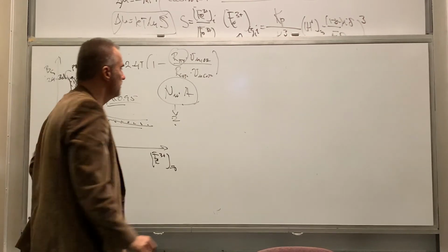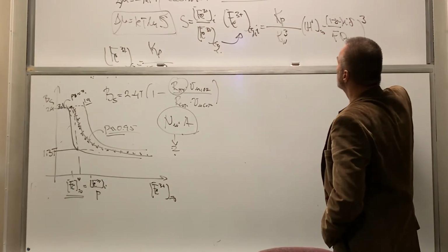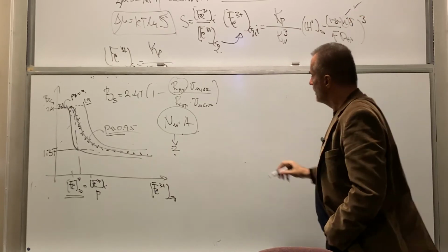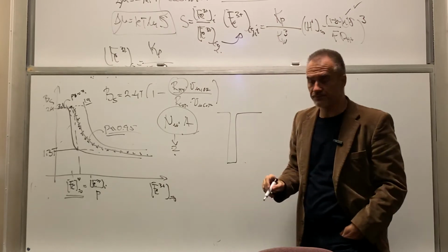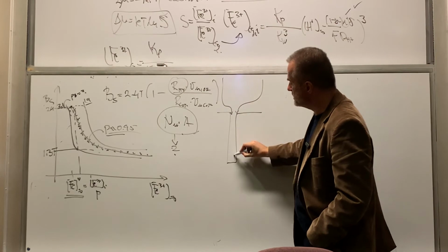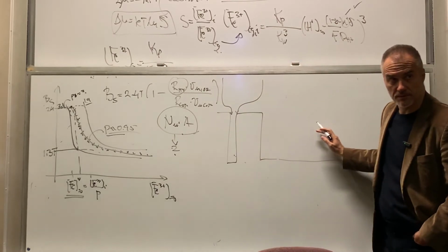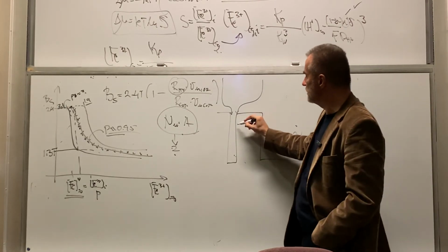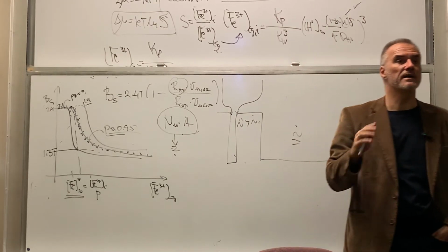We can reverse the story, because here in this equation, if you can see, there's a current density. And I told you when you try to plate in the recess like this, because of the field concentration, the current density in this recess is not the same as current density in open space. Here it's I that we think we have. Here is some I prime which is bigger than I. It's called current crowding effect.